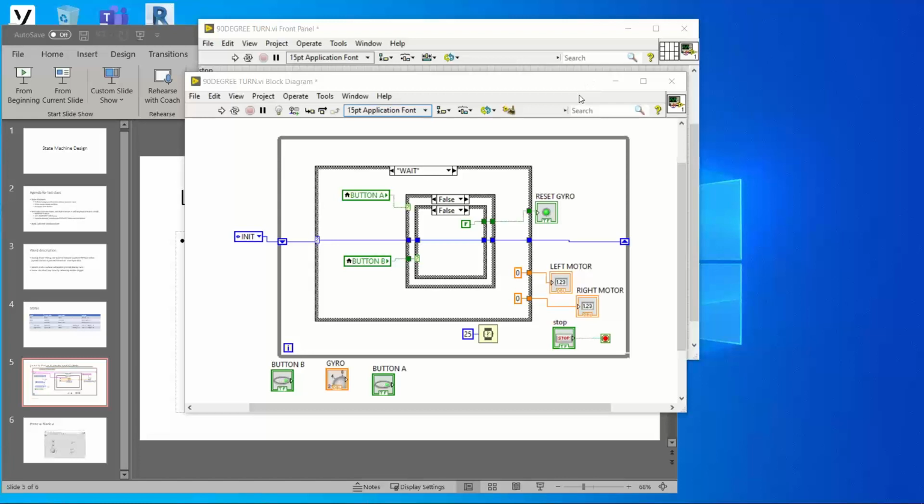So right now, all I'm doing is I want the robot to turn 90 degrees either left or right, and I want the operator to control it with the A or B button. And so rather than him driving the wheels and the motors, the state machine will drive the motor more precisely than you can with your eye, especially when you're sitting across the field from the robot. So that way, if we line up on a feature where the crosshairs on the camera are a known position, and I push the A button, then it does a left turn, and I'm pointed exactly where I want it to point as a result. So let's run this and I'll show you how it works.